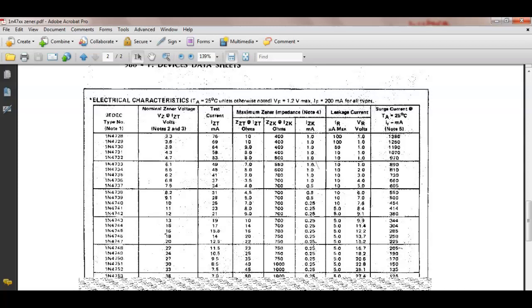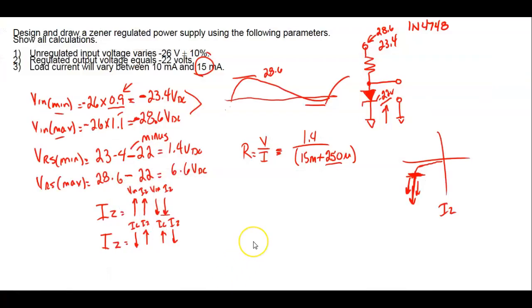Minimum. And that's if we choose; we're going to end up with more than that, because we're going to take this resistor and always do what with it? We're going to always round it down. So if we round it down, Zener current's going to go up, right? You understand that? So what we're trying to do is guarantee operation with all this garbage up in here. So why did we come up with the value of R?